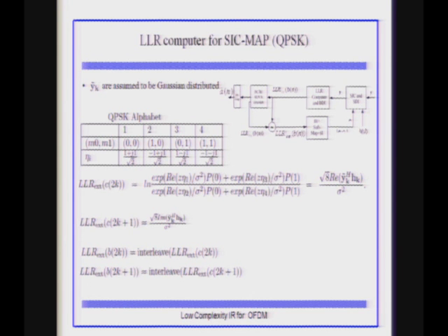If you look at this expression, this is very simple to compute. This is a matrix, this is a column vector with 4L plus 1 elements times h_k. So we are talking about a few multiplications. You remove the interference, and whatever is coming, you compute these values, you get straight LLRs. There is no matrix inversion or estimation, making an estimate of the symbol, nothing is involved.